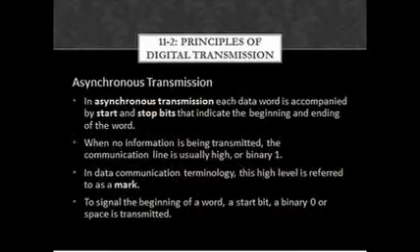Asynchronous transmission. In asynchronous transmission, each data word is accompanied by start and stop bits that indicate the beginning and the ending of the word. In data communication terminology, this high level is referred to as mark. Most low-speed digital transmission is asynchronous. This technique is extremely reliable, and the start and stop bits ensure that the sending and receiving circuits remain in step with each other.